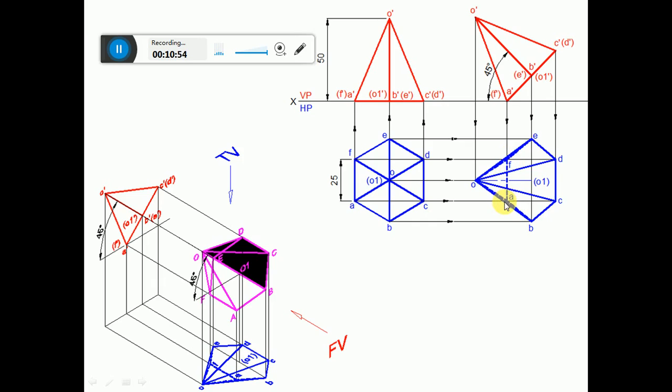Since A is not on the boundary, from that particular point, if one of the edges is invisible or visible, then automatically the other edges emanating from that point become invisible or visible according to the same condition. So here, since AF is invisible, AB becomes invisible and OA also becomes invisible. Similarly, since F is invisible, that is FA is invisible, so FE and OF become invisible.